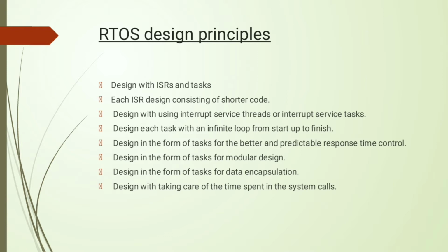When we design an RTOS, it should be designed with the ISRs and the tasks. We should design the ISRs with shorter code, that is, the length of the code should be smaller and as minimal as possible. And we can design the RTOS with interrupt service threads or interrupt service tasks. The ISR, the interrupt service routine, is written as interrupt service threads.